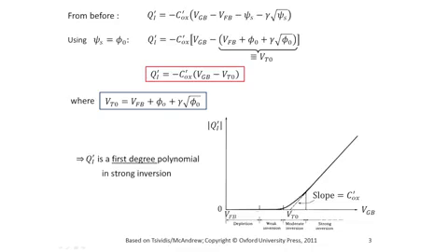So the equation is wrong there, because the exact behavior of QI, if you take our general inversion expressions, goes like this as the solid line. So clearly the equation is wrong over here, but you don't care because we said this is the equation for strong inversion, and strong inversion is from this point on. So the equation is accurate in strong inversion.